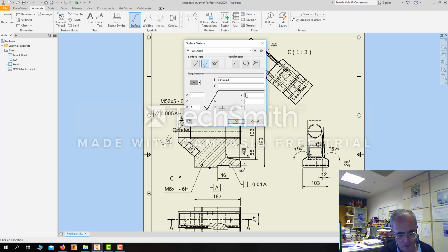Say the roughness with cutoff value is 0.8 millimeters. The process to apply for finishing the surface, say that honing. So write the name in past participle, honed. Roughness value, arithmetical average roughness, to say use this abbreviation, write this abbreviation Ra, and say that it is 12 micrometers.